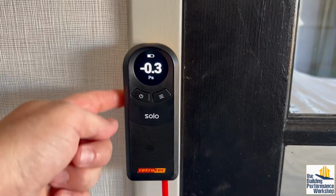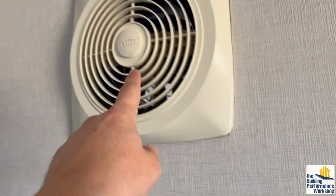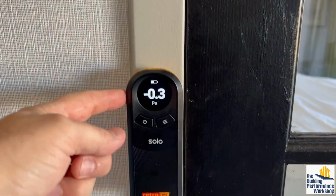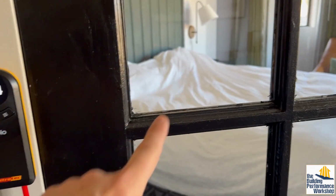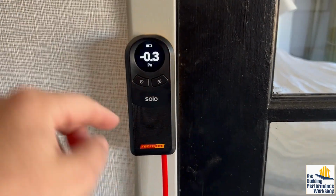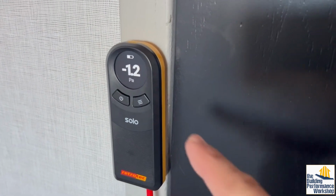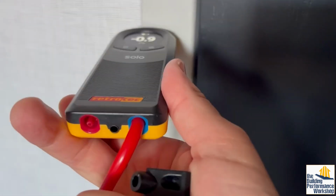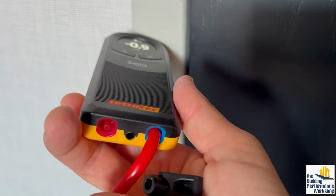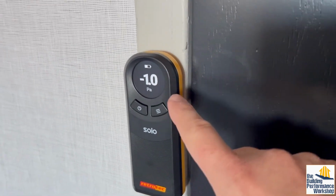You always want to know what you expect to see before you run any test. What we'd expect with the fan off right now is that that room is 0. That room seems to be depressurized, but there's no fans in that room. So likely what's happening is that we're actually pressurized in the room that we're in. Somebody in the hallway is getting really creeped out right now. So it looks like the hallway is depressurized with reference to, again, you always want to know how to say this. The input is in the hallway with reference to the hotel room is depressurized.